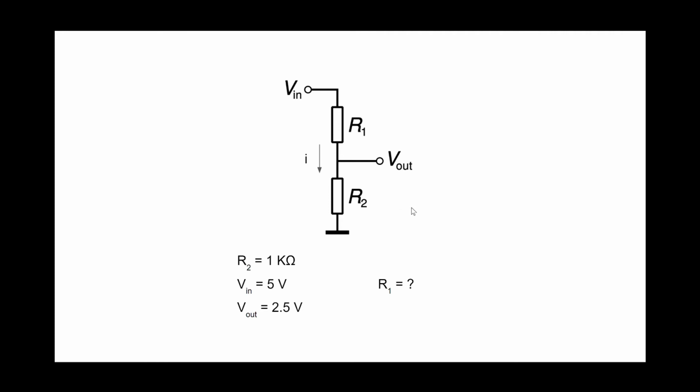What does this mean anyway? Let's assume a situation. Let's say R1 is unknown and the R2 value is accurately known. In other words, you want to measure R1. If you know the R2 value correctly, and if you know the applied voltage correctly also, then you can calculate the R1 value.